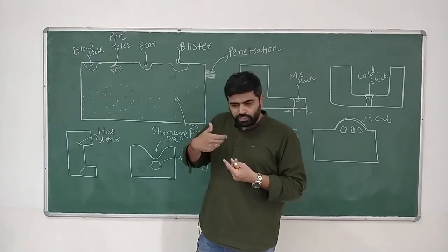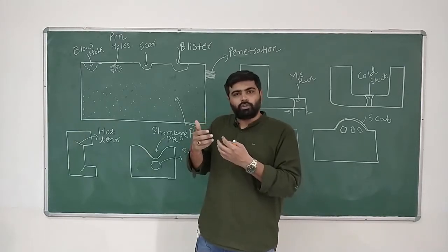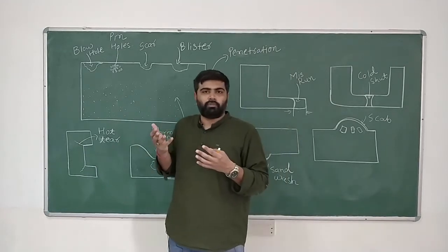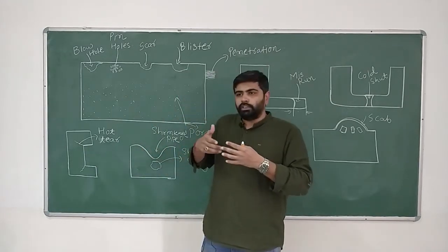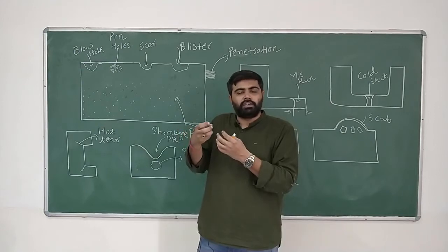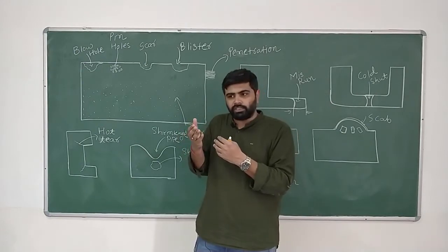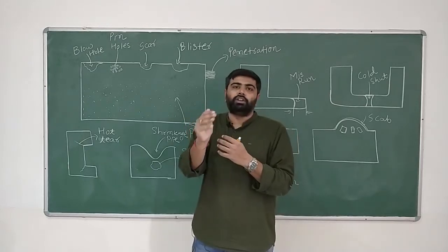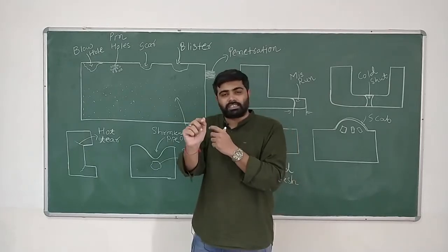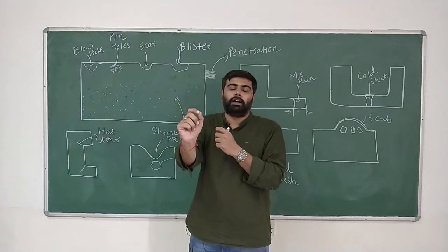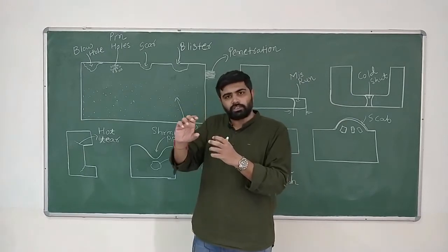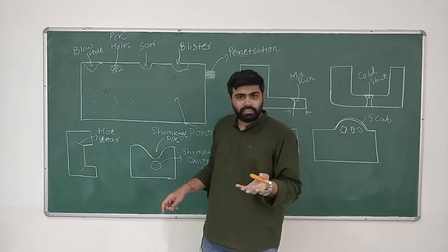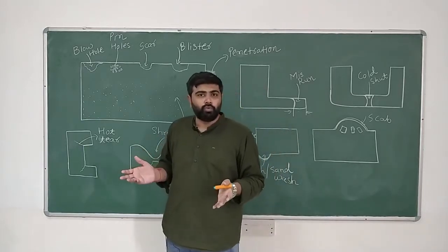And when the residual stresses cross a certain limit, and as we know, stress is one type of energy, so when the residual stresses increase, the energy increases, and that energy actually makes a crack in the component. It tears the casting, and that's why it is called a hot tear or a hot crack. The other reason can be differential cooling rates.